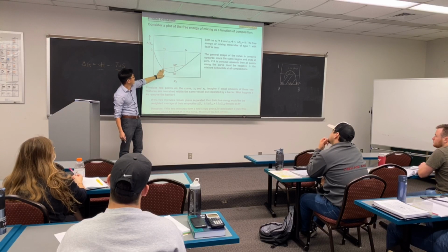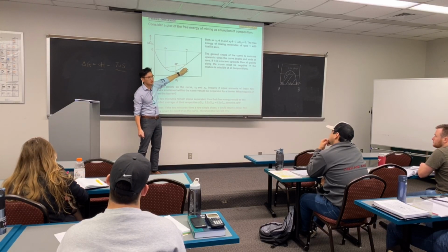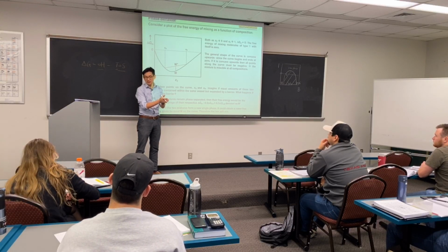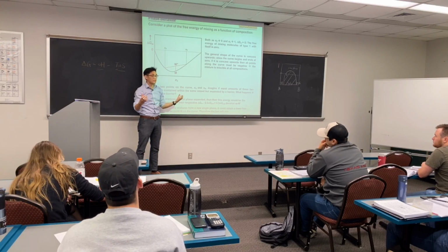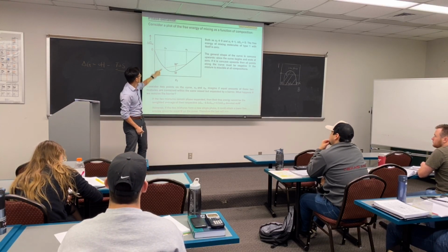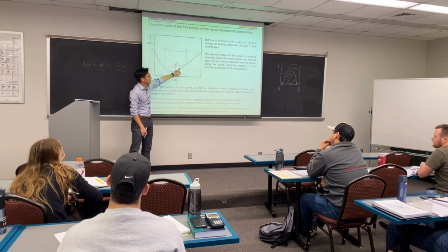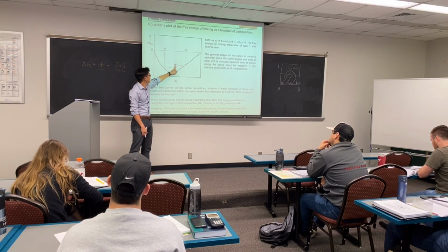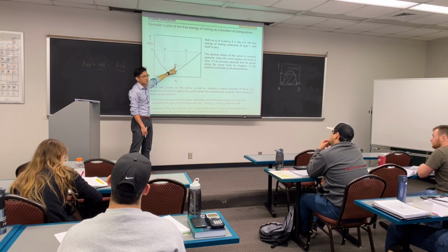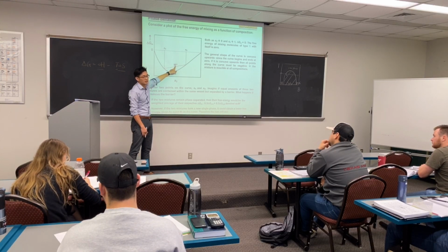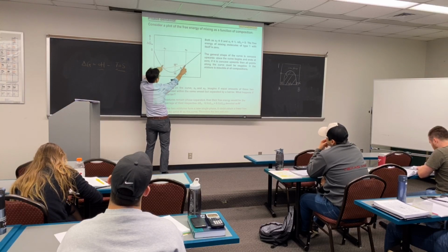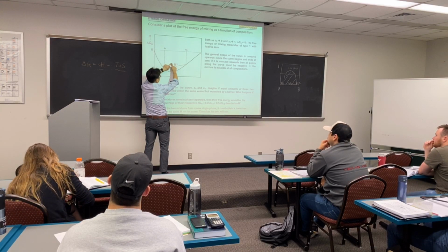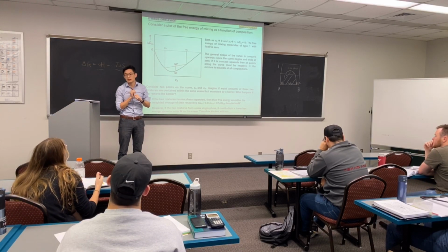This is where component A, component B, when we mix them, what's the system in terms of free energy? It can be linearly calculated because we know component A and component B. It basically follows this red line. It will fall onto this M point. So let's assume they're going to mix, it will be N1, if you just go linearly, right? Or if I give another example, if this is almost symmetric, you have A, B, 50-50, the free energy is going to be the average of the two, right?